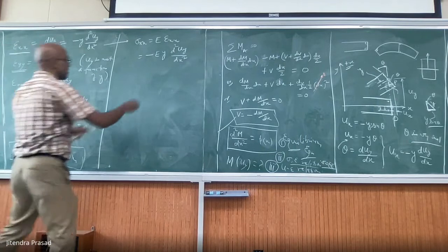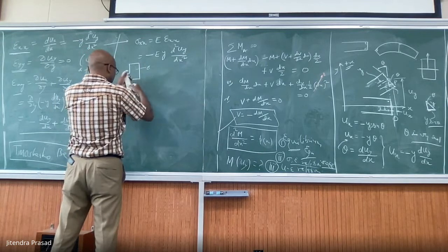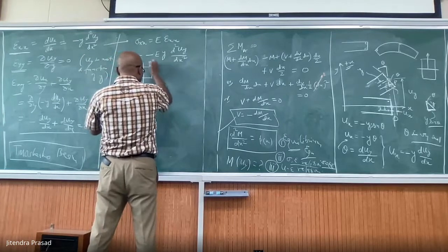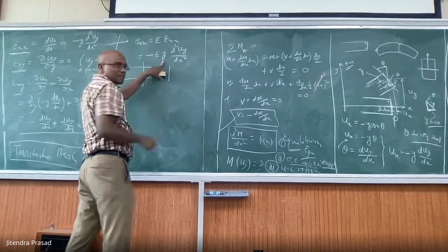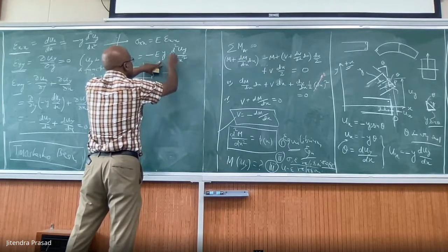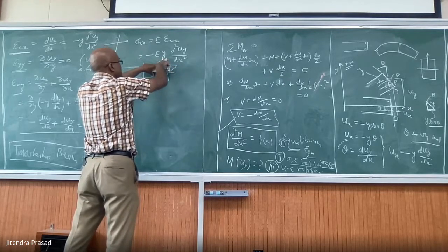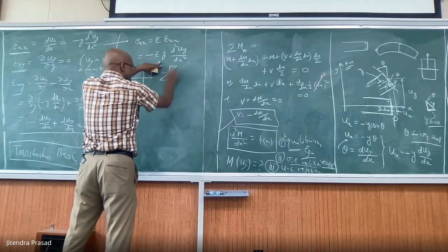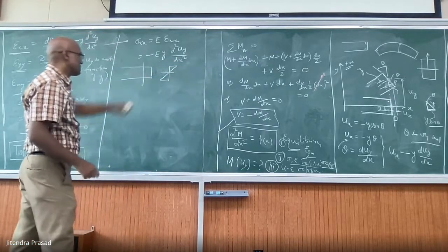But the first thing is, on a section, if sigma x is there, this is sigma x, and this is a beam. We know that with y changes, at some point it's 0, then depending on this value, it goes something like this. That's what it's telling you, right? Because y goes from positive to negative, and hence in y it is linear. The sigma is varying linearly. That's what it tells you.